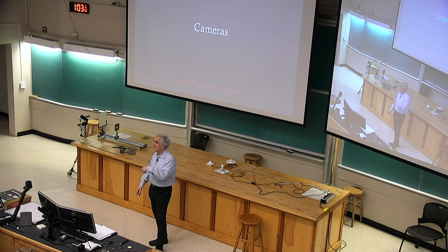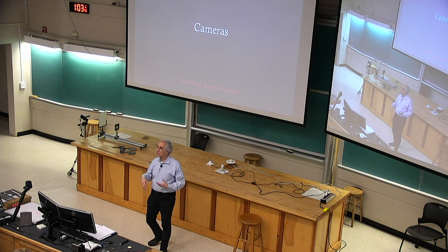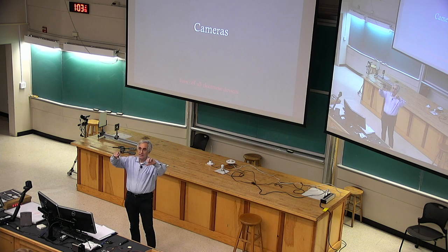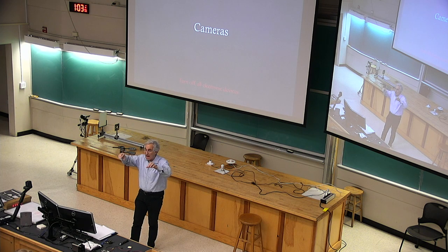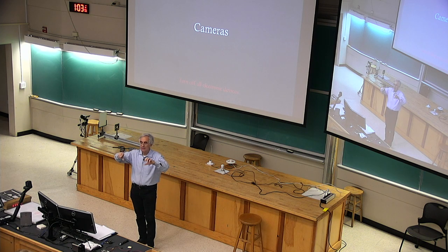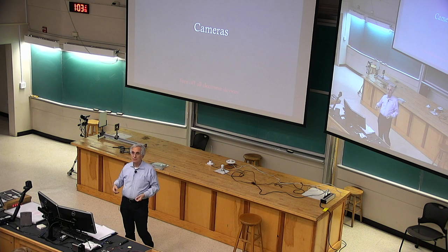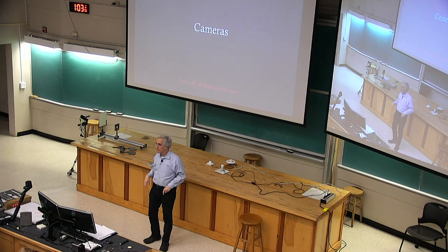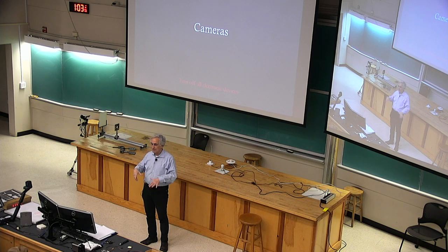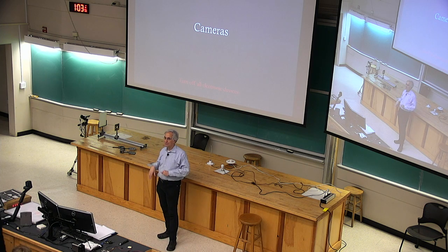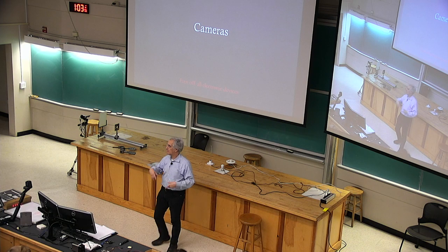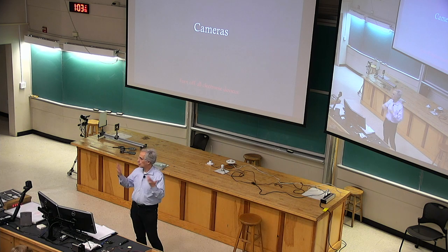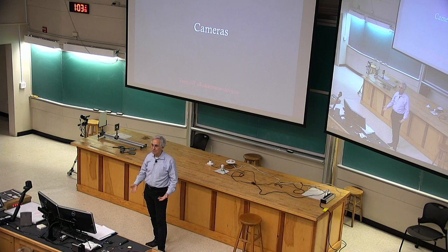Then I looked at LEDs, where we're looking at solids emitting light, and you strategically build the solid so that you end up with electrons in an excited band of levels that has a lot of extra energy, like the conduction levels, and you let them drop into less energetic levels. Again, these are quantum standing waves in the valence band, and in the process they emit light. So people have spent the past 30, 40, 50 years trying to engineer materials and structures out of those materials that as efficiently as possible take the energy the electrons give up in going from the conduction band to the valence band and turn that into light, and into the various colors that you want.